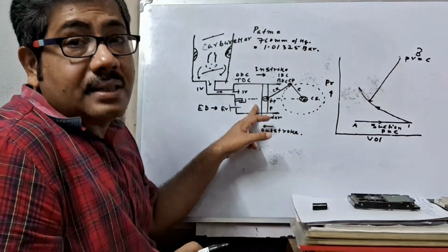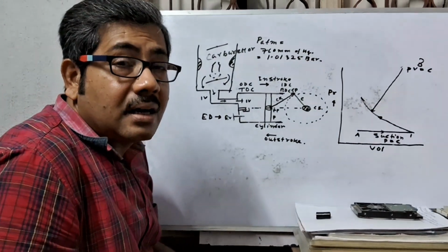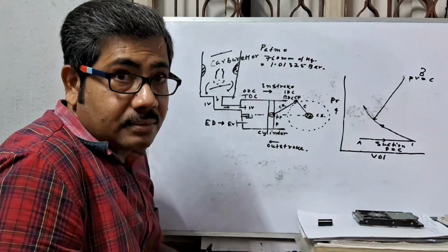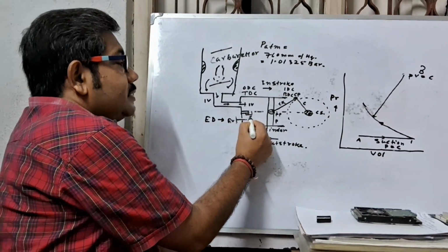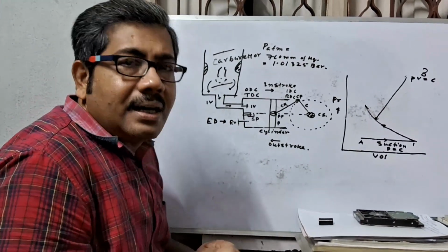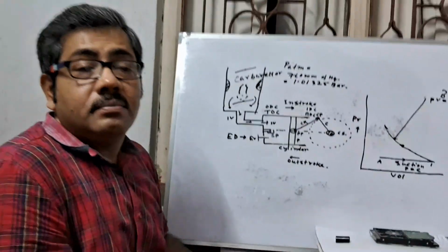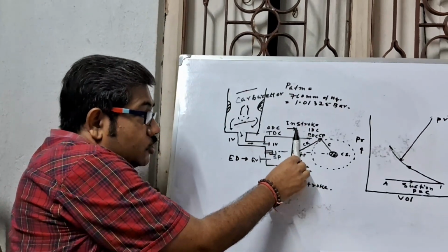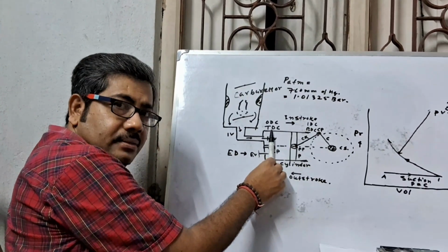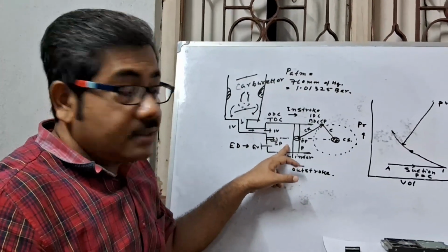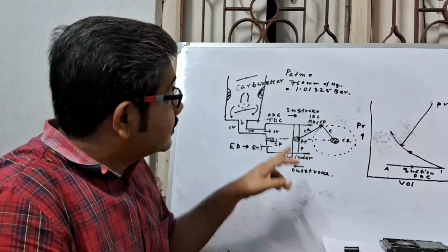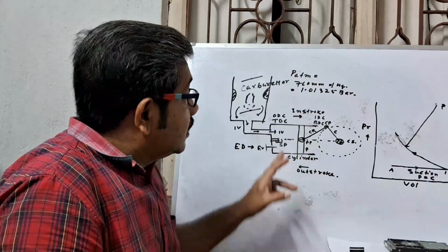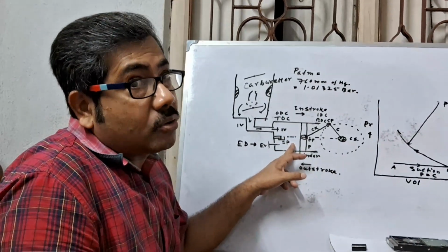And when this heat is near the ignition temperature of petrol, that means at which the petrol burns, then the spark plug, this is the spark plug, burns the air-petrol mixture and combustion starts. And look at the figure. The piston moves from BDC to TDC, that means volume is decreased. But when the spark plug burns the air-petrol mixture, the flame expands, that means volume is increased.